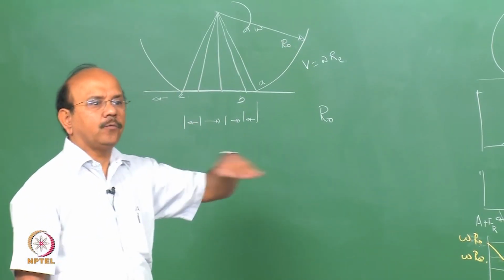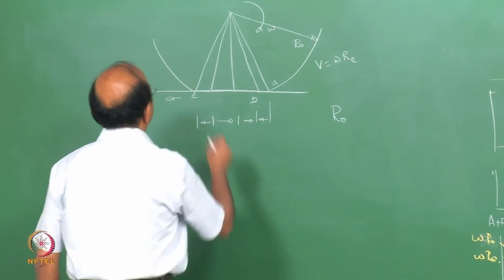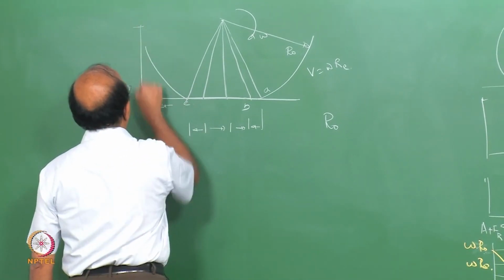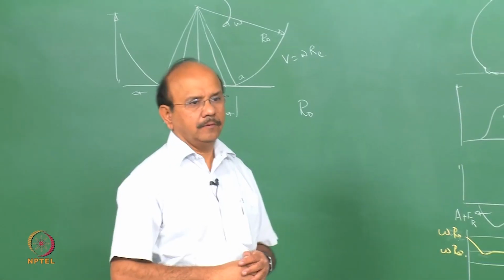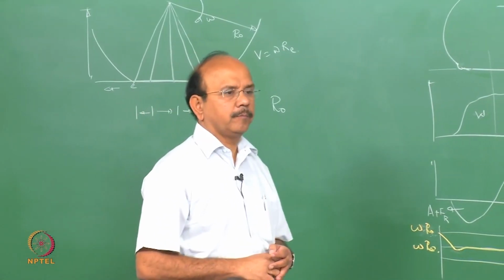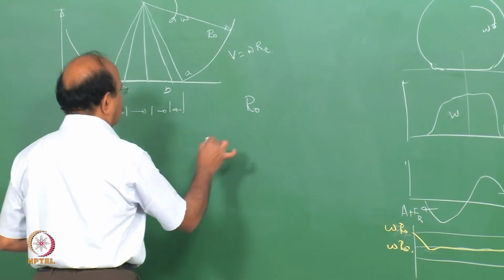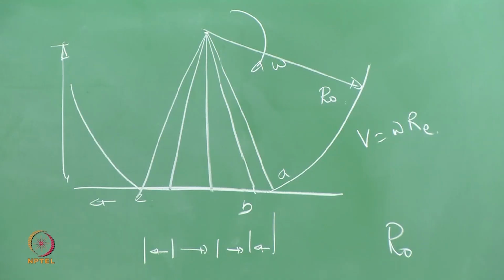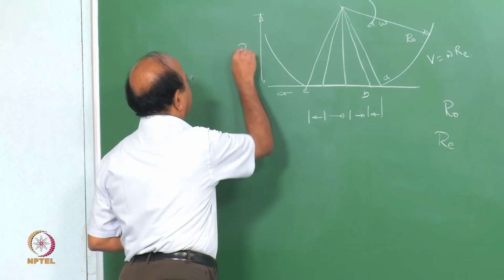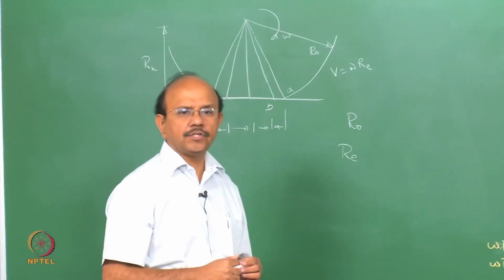We also said that when the tire enters the contact patch, it has a reduced radius, and that in between the two we have an equivalent radius, which I think we called RH.